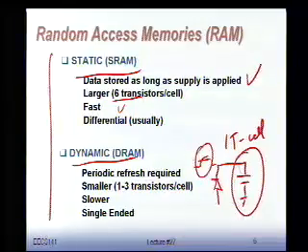This transistor leaks, so charge leaks away, so you have to refresh it. And refreshing is done on a regular, periodic basis, when your memory is sitting there not doing anything. You read a word, you decode it, and you write it back into the memory. That's what refreshing is: replenishing the charge that was lost. You read, it leaks away, you read it again, you write it back, you replenish all the charge. That's just creating some overhead with DRAM memories. But as I said, they're a lot smaller, a factor of 4, 5, 8 smaller than, let's say, a static SRAM cell.